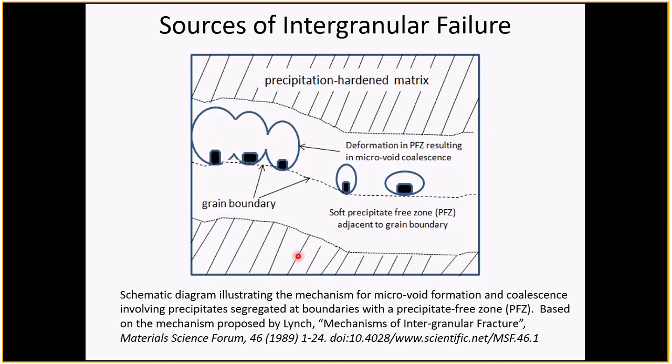Actually, I don't know, I'm guessing now, but I've read that precipitating carbides on grain boundaries is by design in some cases, where having carbides along the boundaries makes the material more resistant to high temperature creep by grain boundary sliding. So that's a very special kind of set of circumstances where the material might be operating at a very high temperature.